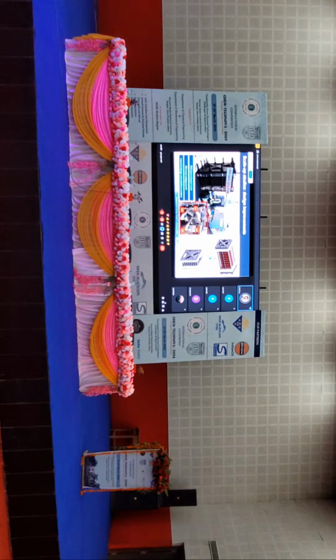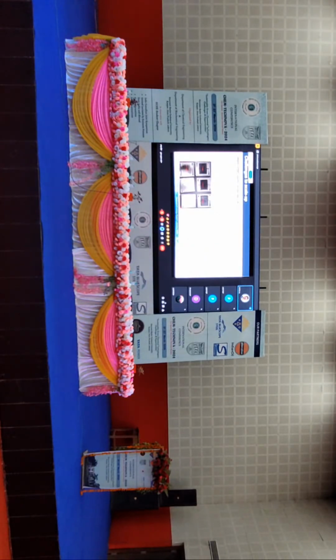So minimum leakage points; this is an industrial design and suitable as a product. Once we were scaling, from a single cell of maybe 10 square centimeters, we are going to more than 1000 square centimeters. Presently we are working on 1500 square centimeters. We have observed that once we increase the size of the electrode, there is a problem of shunt current, and therefore the bipolar plate that we are using shows degradation.